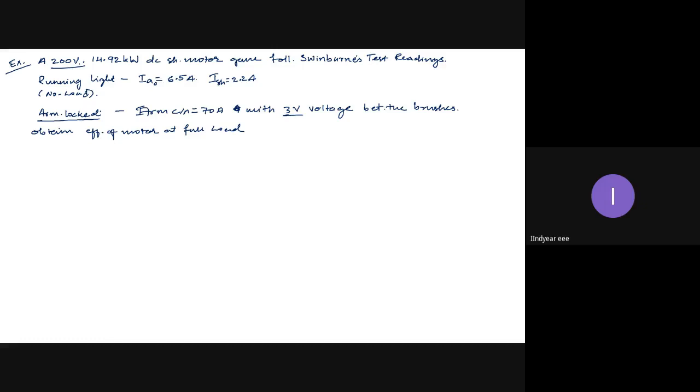If you apply full rated voltage under blocked rotor condition, then my winding will burn. The same thing we observed in transformers, where the short circuit voltage applied was hardly 20 volts, where the rated input voltage was 230 volts. Conceptually all the tests are the same, only the way we conduct them is different depending upon the machines. So understanding the open circuit test and short circuit test conditions is very important, in rotating machines as well as in static machines.